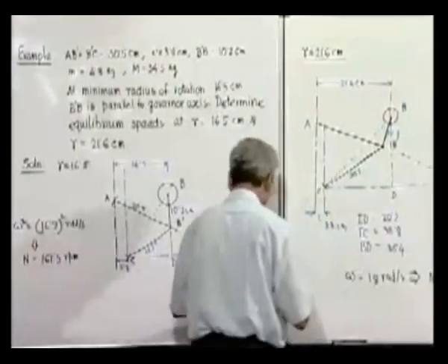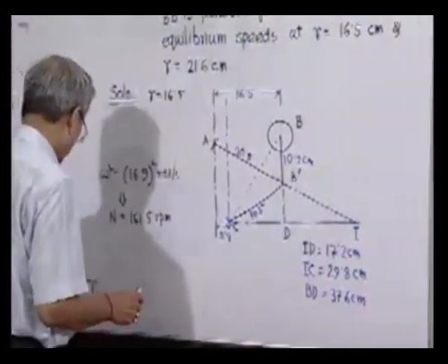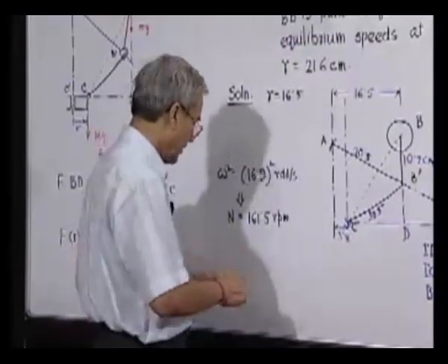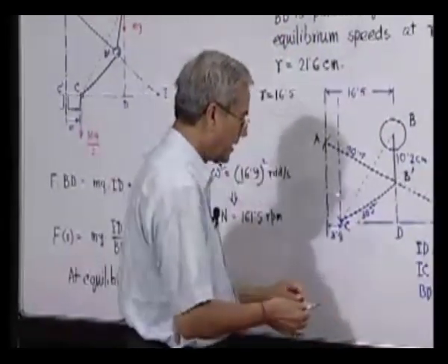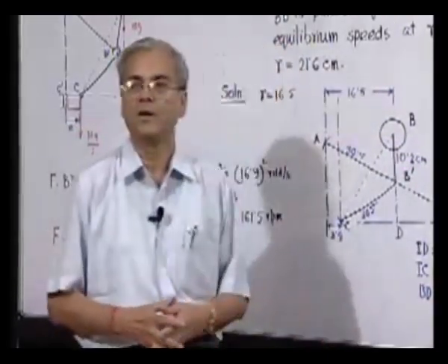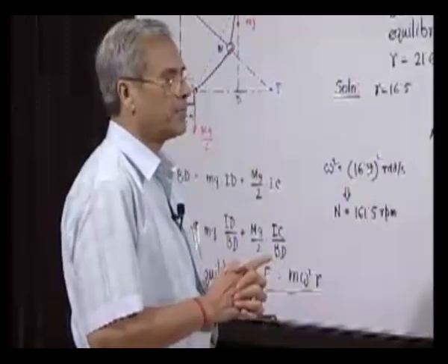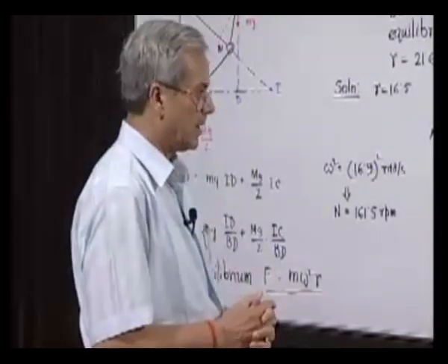On the other hand, as I already mentioned in the previous lecture, the system can be much more compact, lighter, etc., with much better control, when we use springs for controlling the governor mechanism. So, next we will take up the spring controlled centrifugal governor.